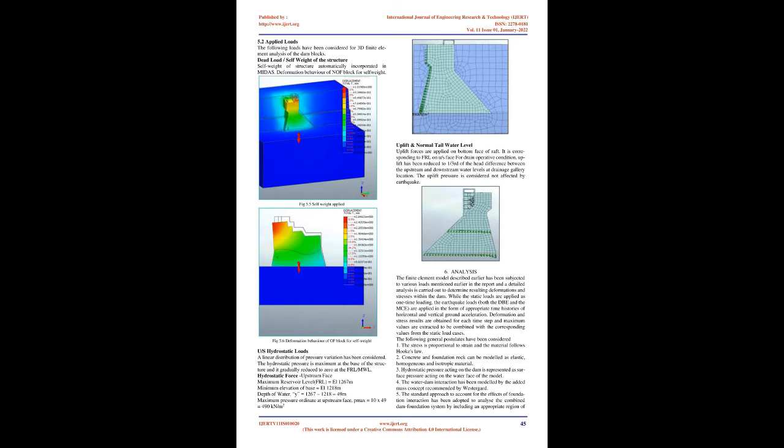5. Software modeling. Midas Civil NX has been used to model the left NOF block structure. The mass concrete structure and surrounding rock have been modeled using self-generating solid mesh in Midas. Mesh size of 2 m has been used for dam body and coarser for surrounding rock in the Midas model. After conducting various sensitivity studies, it was found that mesh size of surrounding rock has no major impact on induced stresses of dam block. Hence, coarser mesh size has been adopted for rock to decrease analysis time.